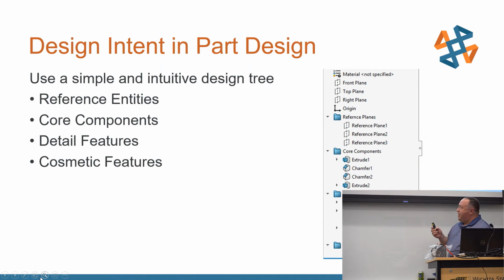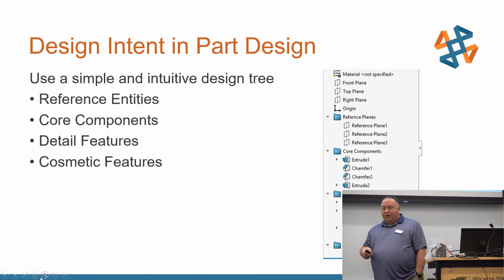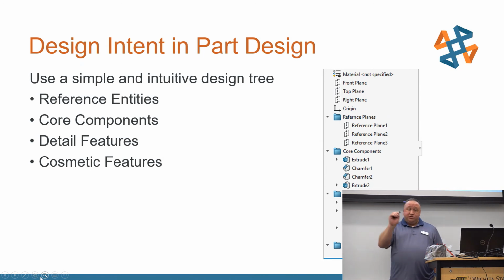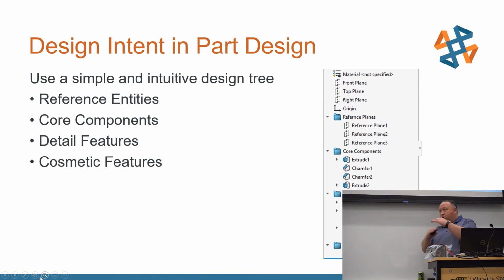Another option that has been out for a number of years, and this doesn't break parent-child relations like you might think it would, is creating folders in your feature manager tree and then moving features to those folders. SolidWorks knows that this feature is a child to this feature in another folder, so it keeps track of all that. But it makes it easier for you to organize and maybe group or simplify your tree by creating these different grouping folder names. And again, you can call these folders whatever you want.